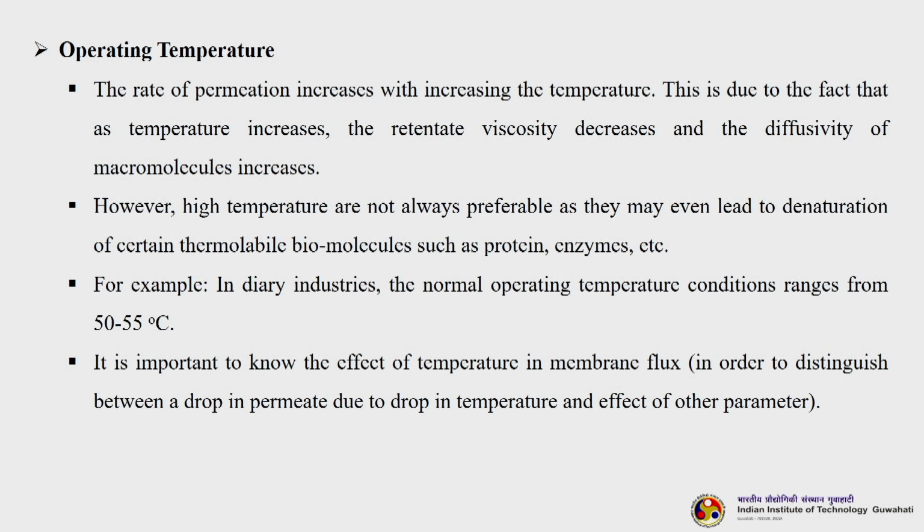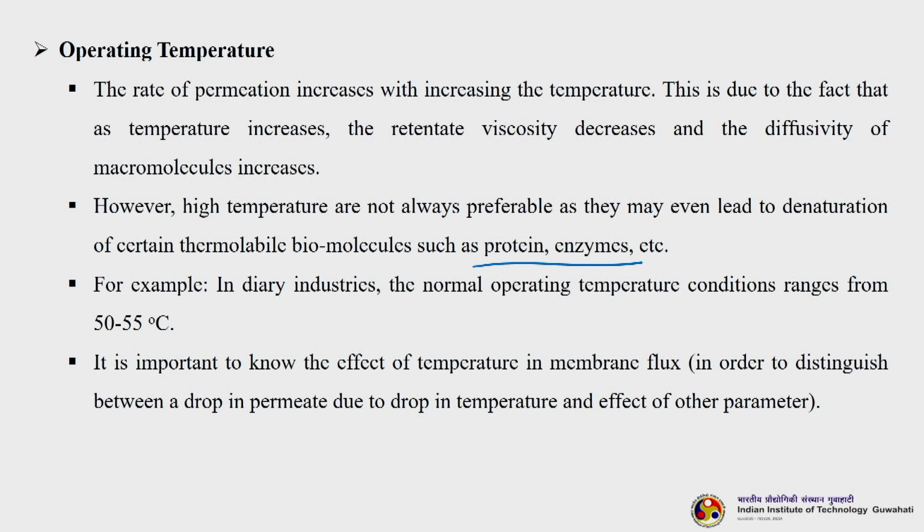Now, high temperatures are not always preferable, as they may even lead to denaturation of certain thermolabile biomolecules such as proteins and enzymes. Whenever I am doing some bioseparation, I cannot of course increase my temperature. For example, in dairy industries, the normal operating temperature ranges from 50 to 55 degrees centigrade, and another important thing is that the membrane which you are using should also be thermally stable.